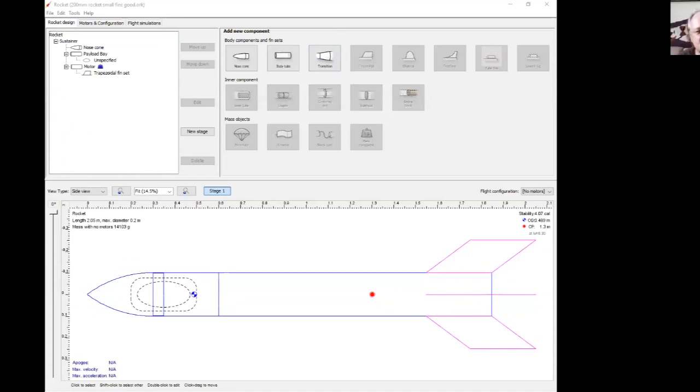I've just got a whole lot of questions. In your professional experience, why do you think that toy rockets, as Mark called them, the Cesaronis, have such low performance compared to the kind of things that you guys work on? Okay, there are several reasons, but many of them are reloadable, which means that the case has to be manufactured much more strongly and with removable enclosures, which will mean screw threads and so on.